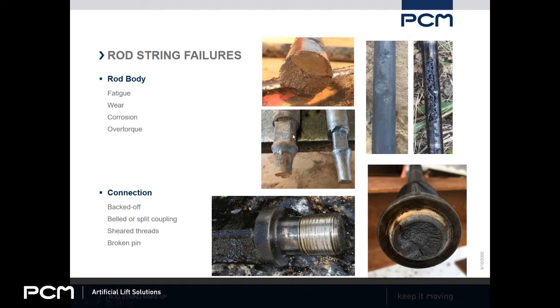But that's where you're going to see fatigue failures most of the time. Corrosion, obviously. Here's a couple of pictures of corroded rods. If you get a lot of corrosion in your wells, it's going to reduce the strength. You'll often get fatigue failures starting at these corrosion pits in the rod. So the final failure may actually be a fatigue failure, but it's clearly related to corrosion. And you'll especially see that with continuous rod, although it can certainly happen with standard rod as well.